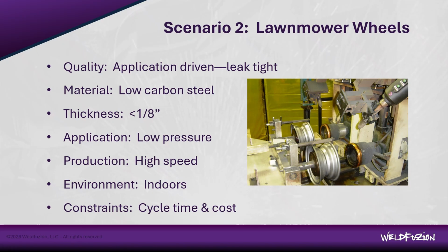And this company was doing everything they could to achieve the necessary quality at super fast speeds. Like I'm talking 100, 110 inches a minute kind of fast. In fact, in this case, the company was upgrading from a short circuit MIG process, and they were implementing new technology called pulse MIG, which would help to pulse into a spray transition and control spatter without putting in excessive heat. So we were seeing a big upgrade here in terms of process capability from standard MIG to a waveform